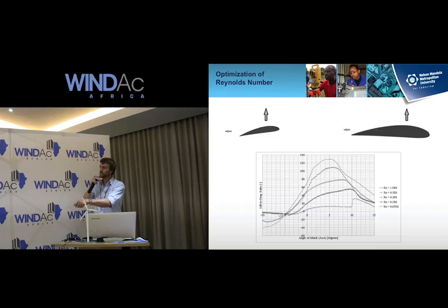Okay. So say we're operating on this Reynolds number curve, and we're operating at our max lift to drag point there. I've now said that, okay, we've reached the top of the scale, we can't go any higher. Let's increase our Reynolds number so we jump to the next curve, because there's an advantage in lift to drag ratios there. But I've had to decrease my angle of attack maybe to there. So now I'm operating at that point there. Low angle of attack, maybe a similar lift to drag ratio. Okay, and we see this in this next slide here.